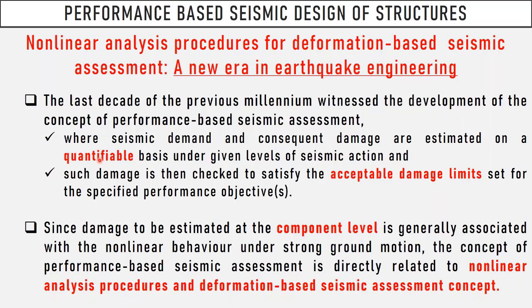And we do it at a component level, which means that it's not a kind of global estimation, but component by component, beam by beam, column by column, shear wall by shear wall. We check this quantifiable damage against the damage limits and say, okay, this component is acceptable or not.